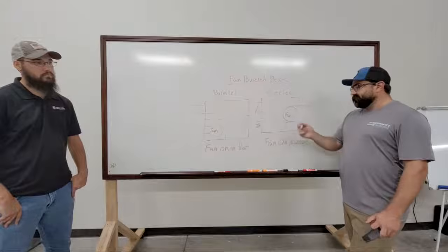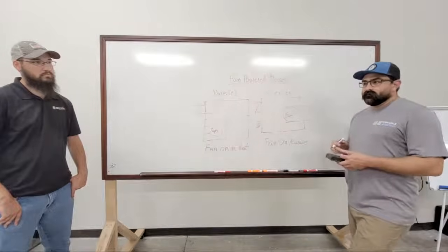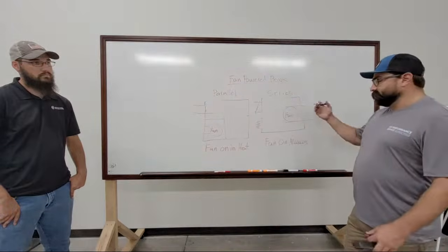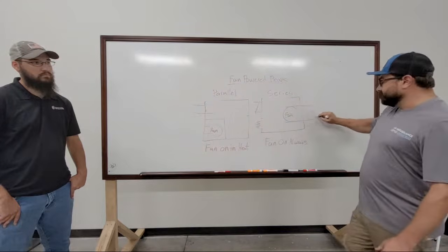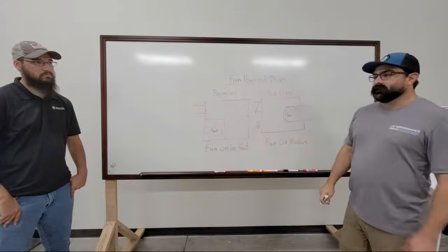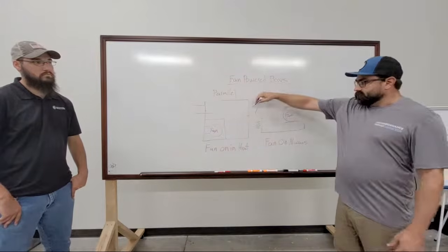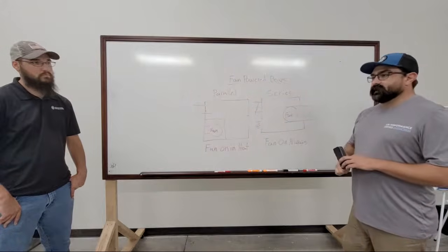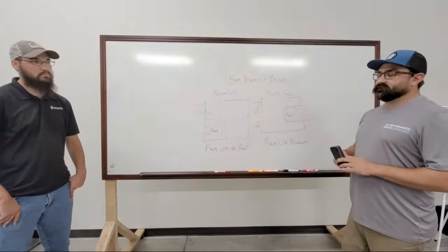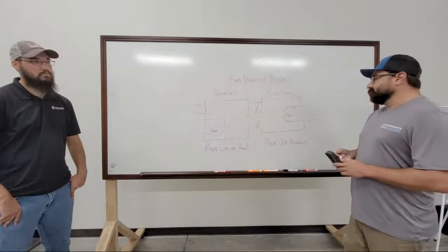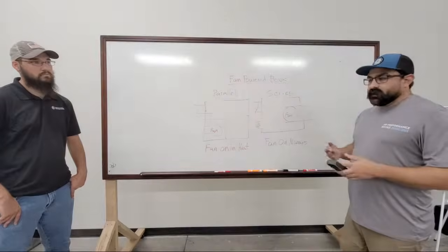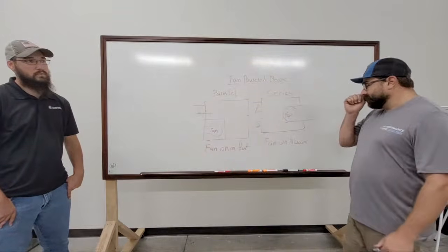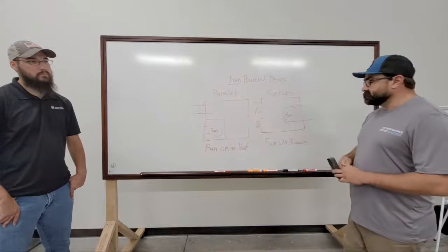If someone shuts this fan off for energy savings, they may save energy, but at the cost that you're now not sending air downstream, it's blowing out the back of the box. You're wasting your cooling. You're just dumping whatever temperature air right back into the return. The unit's going to short cycle. You're not going to cool the space temp, you're only going to cool the return. You're going to have temperature problems. So you may save energy, but you are going to have other problems. Basically, you won't cool your space.